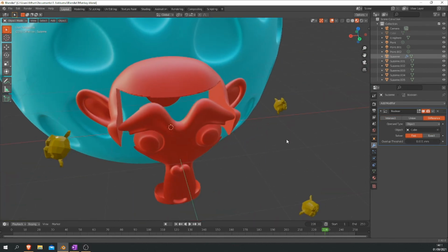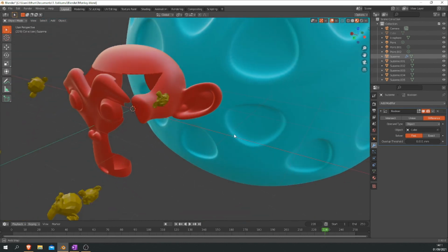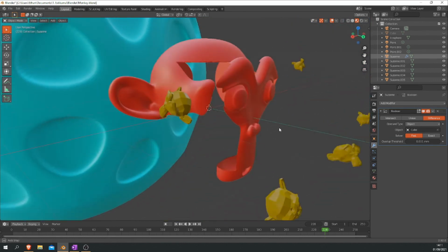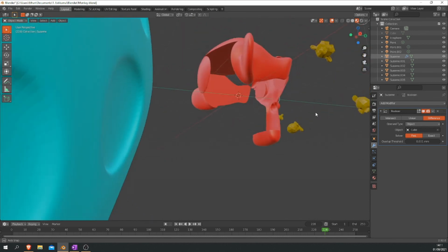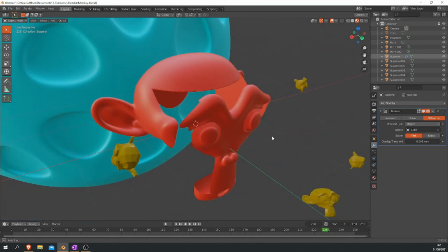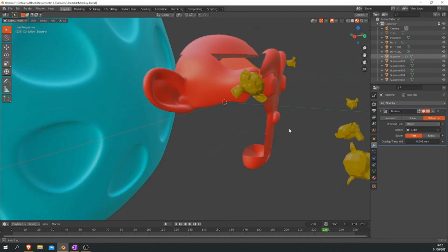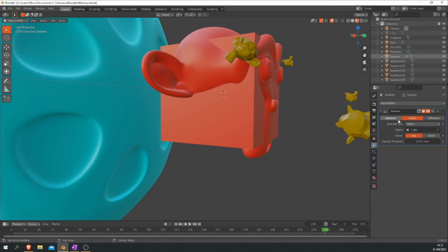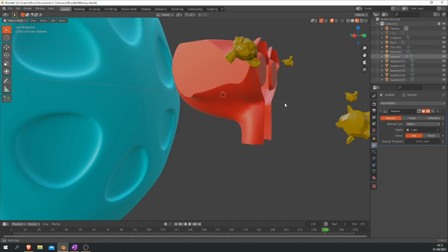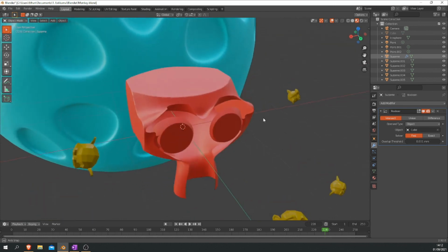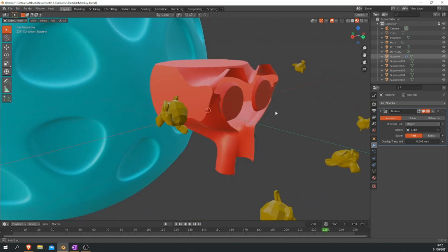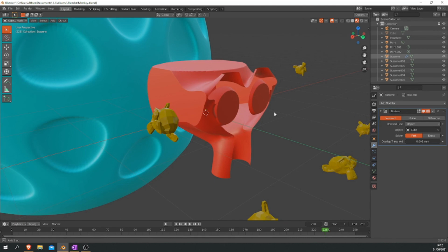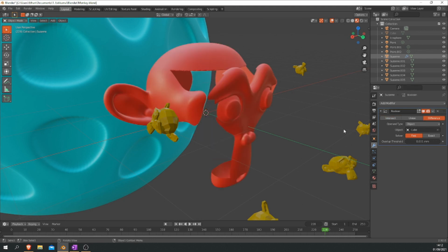And yeah, so there you can see now I've just put it on difference and fast, because being exact would take a little bit longer. But where the cube was, it has taken the difference away. So now we have an internal view of the monkey mesh. Union obviously will just join the two together where they are, and intersect will basically keep everything. Oh, that's creepy. Every part of the monkey face that is inside the cube is kept, while everything else outside the cube has been deleted. I'm going to go back to difference because that's better.